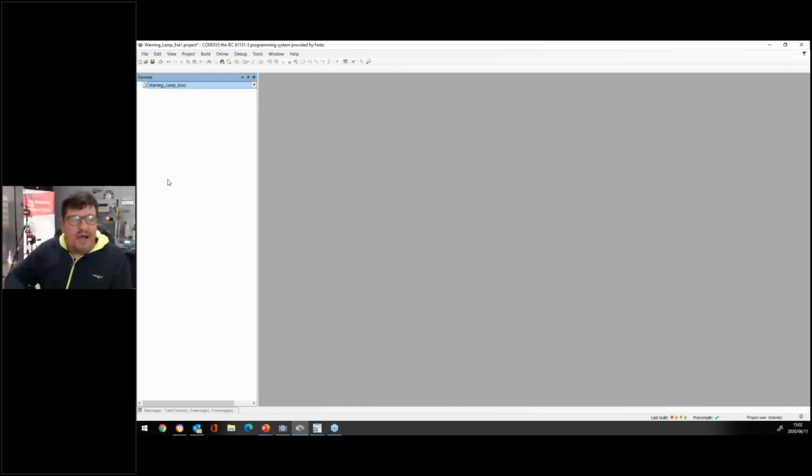Right. Now, guys, after I've downloaded it and installed it, I'm going to right click onto it. Now I want to add the device. That means my first step when I start a project in CoDeSys is to add a device window. This is my device window right here. Then on the device window, I created my project name. And on my project name, I'm going to right click onto it. It will give me a drop down menu, and I click add the device.